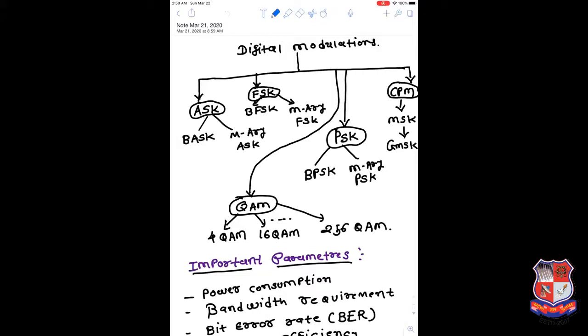So we have discussed over there the baseband signal is binary in form, which is a low frequency signal, and if we are transmitting that signal directly without the modulation, then at the receiver side we need a larger antenna to receive the signal, and in some cases the size of the receiver antenna is in kilometers, which we cannot afford.